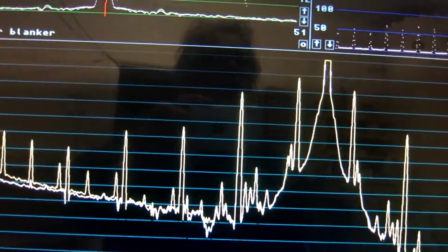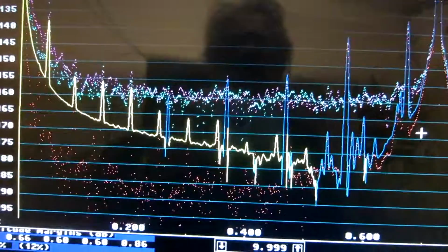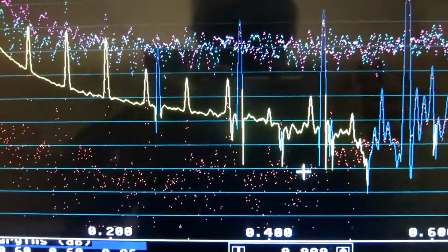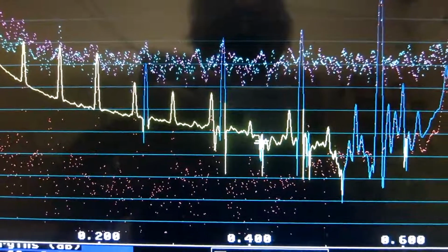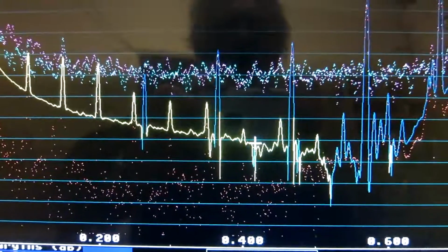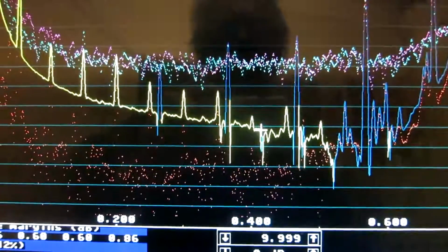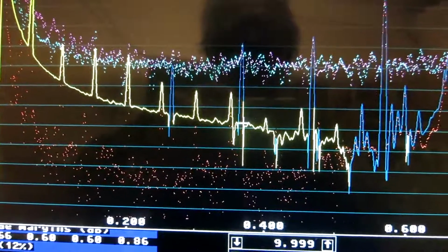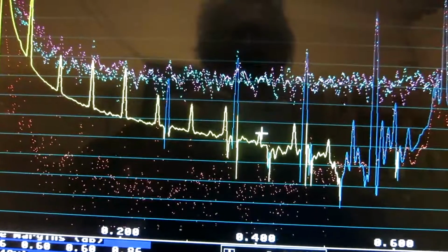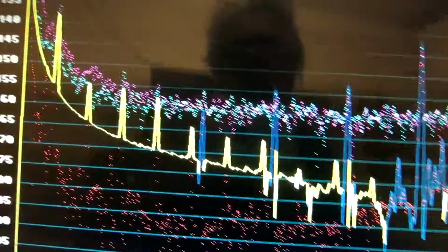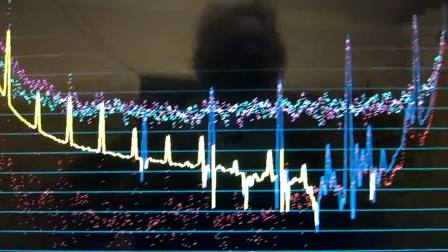So when looking now, I go for the complete information. I can see that here is some kind of spur. There is a peak here. So I have a problematic situation. The spur is negative in sign. But it looks like I can trust values up to 400 Hz. It's this little peak where I see minus 175 for the phase noise.